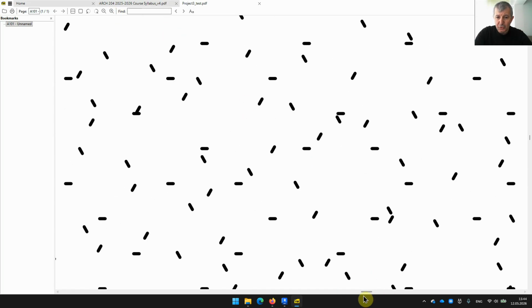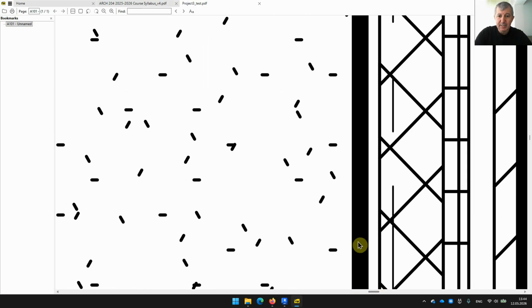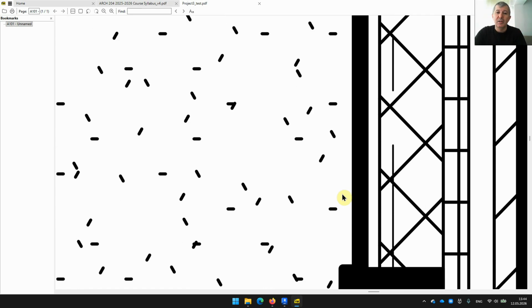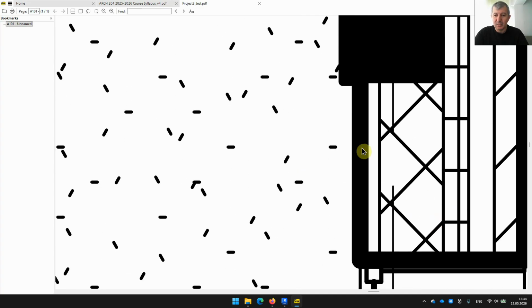So what you do is, if you take it to the print shop, you tell them to print this at 1 to 100, like 100 scale, perfectly, because this is A3. You can say that this is the A0 size paper, and then print it on A0 paper, or make sure that it's printed at 100%. If you do that, then it will look nice and crisp, because it's vector based, it's clean. Okay, so that's the idea.